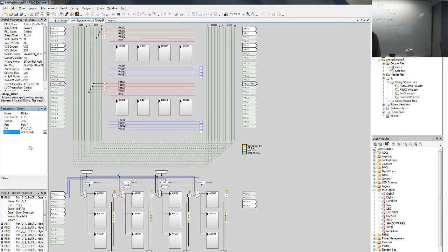So these modules just give you easy access to the physical thing that there is inside of the device, but it's this code that tells what to do, so you can overwrite everything by your own code. Okay, so port 1 pin 1.5 is now there, named Blinky.